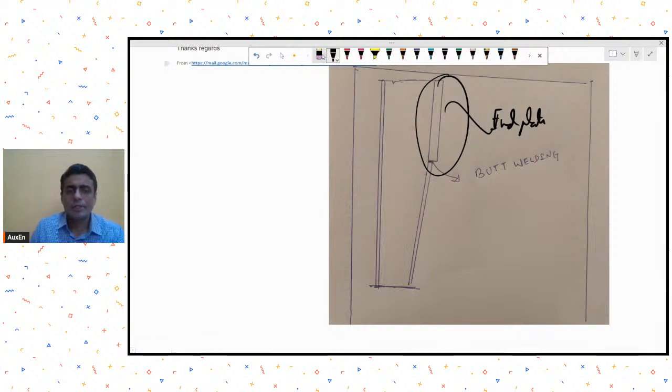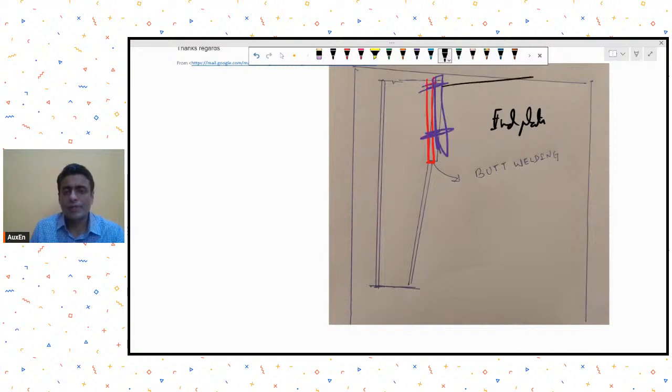No, this has to be first. There has to be a column flange over here. To that column flange, an additional end plate will be bolted by the use of extended end plate connection, and of course the beam is welded to this end plate. Okay.